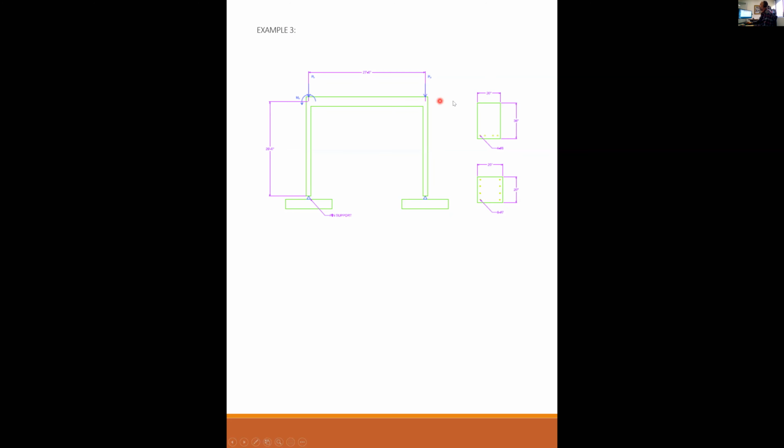So this frame is leaning on something else to give it lateral support or stability. And we're just trying to analyze if this column has slenderness effects, if this column has a tendency to buckle. We're analyzing how much to amplify the applied moments to make sure that we're still safe, even with these tendencies of slenderness. Okay, just a refresher, this is what we're talking about. And this column has 8 number 7s, all 4 of them on each side face in this direction. And this is a section of the beam.